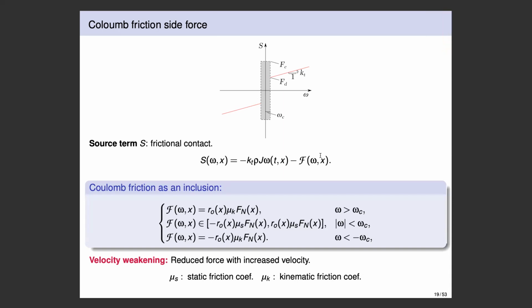Yeah, I was going to say I can't help. I noticed that one of the models, or one of the things you modeled, is an S-shaped curve: build, hold, drop. That is notoriously difficult in terms of stick-slip off bottom, and I think it's partially that curvature effect, the extra tension that you get in the string around those corners, or the contact force. So I waved my hands and said that that's the case.